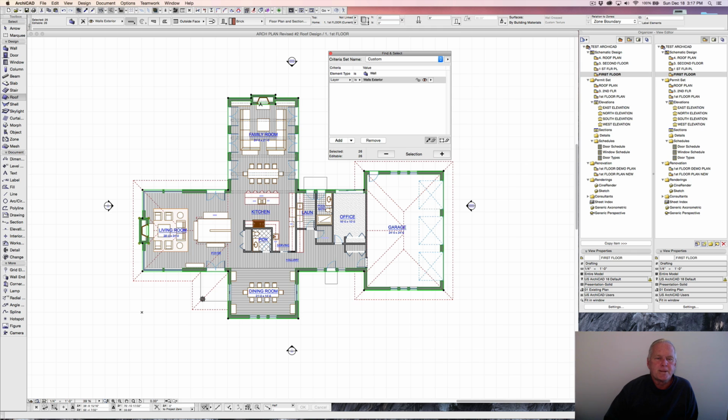Now, even though they might be a different profile, we still want them to start at the top of foundation, and when we go ultimately to put in a foundation underneath all of this, we're going to set the top to be 0. So we have to think now in terms of, instead of being a base at 0, we want to be down to the top of foundation.